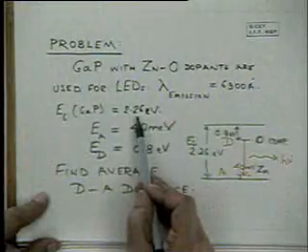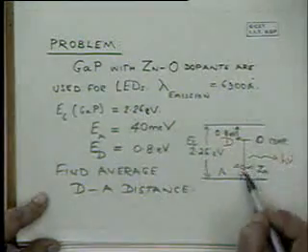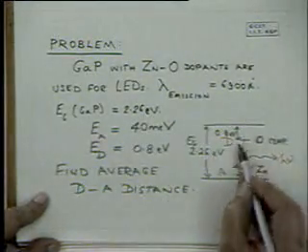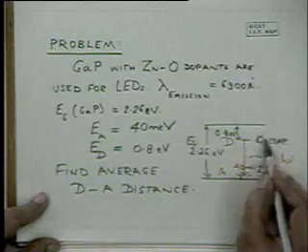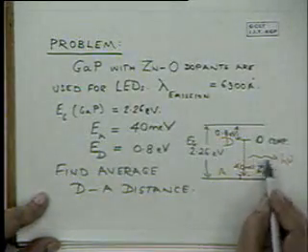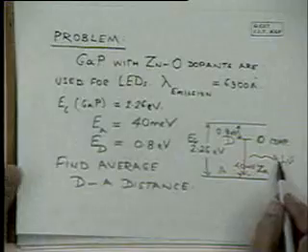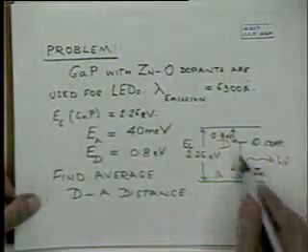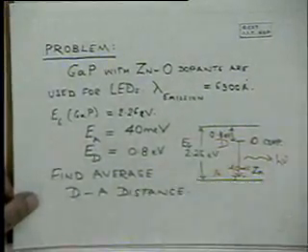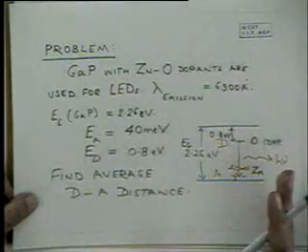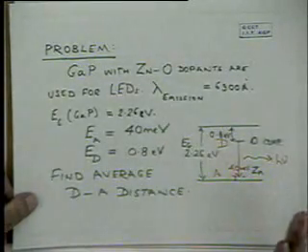So this is an example of this donor acceptor pair recombination, and you can see that although the band gap of gallium phosphide is 2.26, you are getting red emission due to this. Oxygen is the donor, this is the acceptor, and in this case you are getting red emission. As I mentioned last time, because gallium phosphide has a wide band gap, you can get the whole spectrum from green, yellow, orange, red.